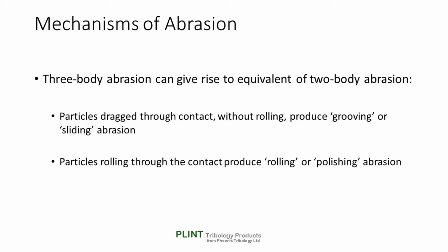Somewhat confusingly, three-body abrasion can give rise to the equivalent of two-body abrasion if the particles are dragged through the contact without rolling, as opposed to rolling through the contact. The former gives rise to grooving or sliding abrasion, and the latter to rolling or polishing abrasion.